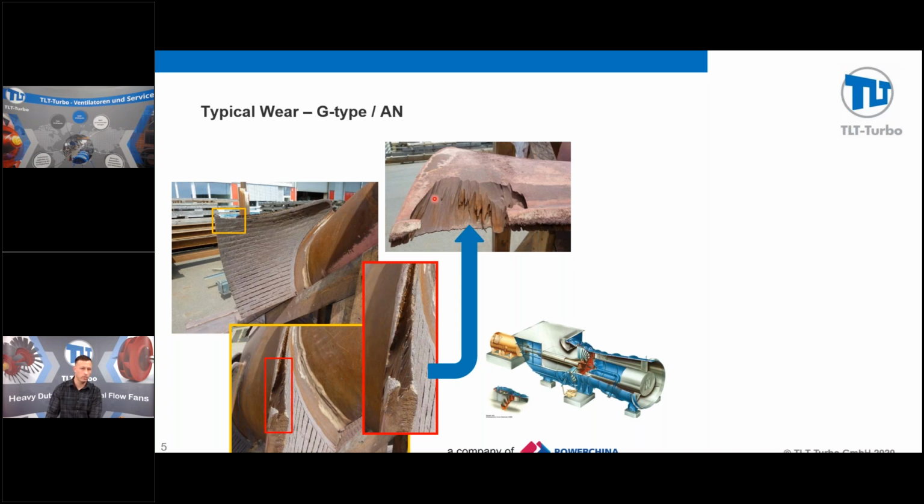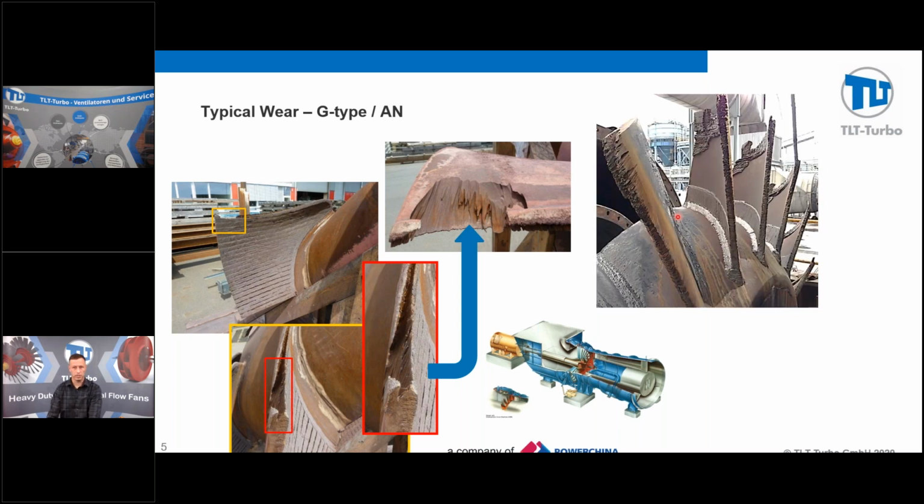And as it's working, you can see where it's more aggressive here. It's a little bit less, but you can see that's working in a pattern down the fan blade itself. So as it's removing material kind of uniformly down the fan blade. Now, the picture on the right is a very severe case. And you can see that all of the leading edges are heavily eroded. And then you also see that a lot of the wear protection is eroded off the fan blade as well.